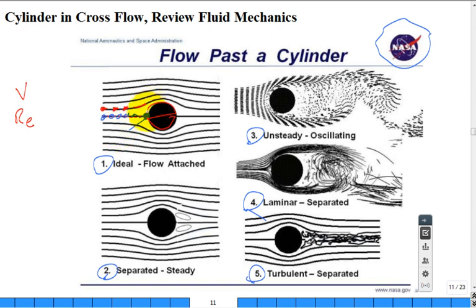All right. Now let's continue and go around to the top part. The same little fluid packet, let's say it goes to the top. It was headed for the middle, now it diverts, goes around to the top. What happened to the velocity as it went from here to here? What happened to the speed of it? Increased. It went faster. How about the pressure? Down. Actually, that's the location of the lowest pressure anywhere in the system, on the top and bottom of that cylinder.